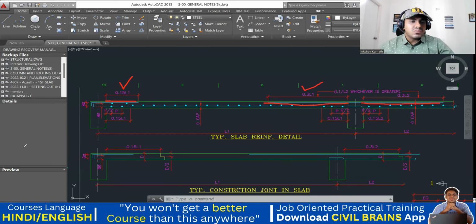Apart from that, even the bottom bar here. This is your bottom bar that you provide in the slab. Usually we don't do it like this; we actually provide it full only, but still okay, they have given it like that. If you're providing a bar like this and you are curtailing, then from here you leave a gap of 0.15 into L1, and from here you leave 0.15 into L1. Okay, fine. Got it? This much is understood.